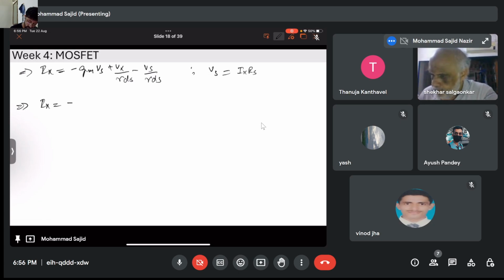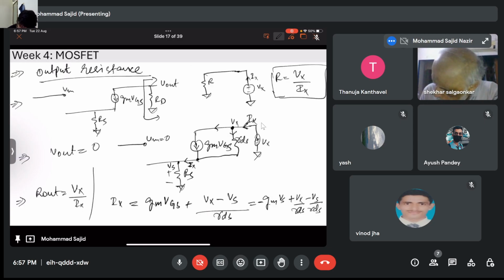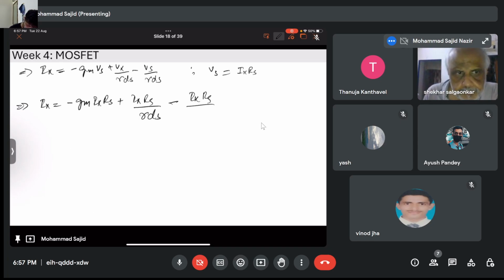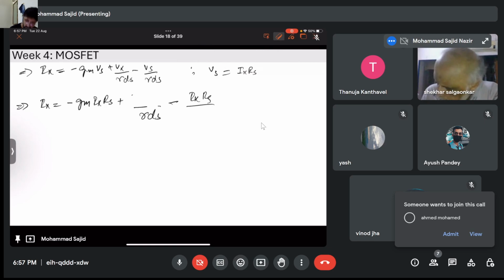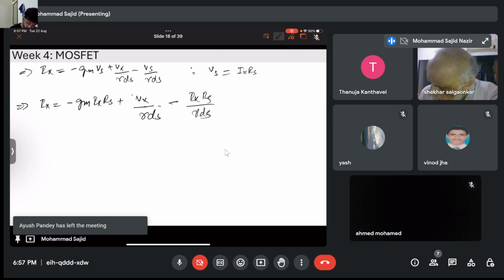So my Ix is Gm Ix Rs plus Vx by Rds minus Ix Rs by Rds.